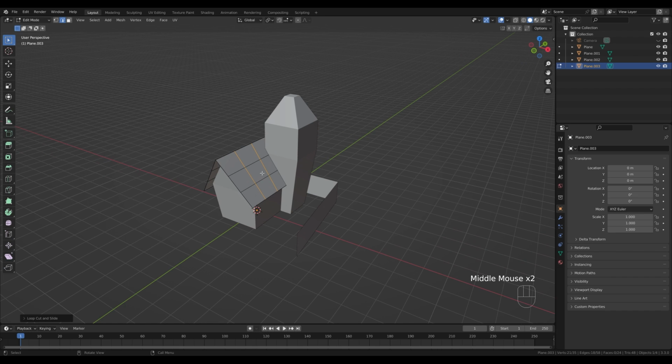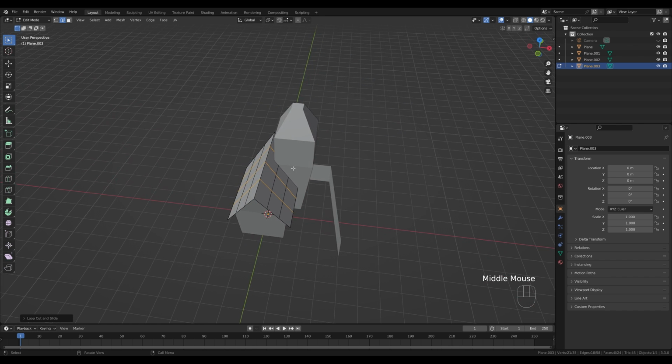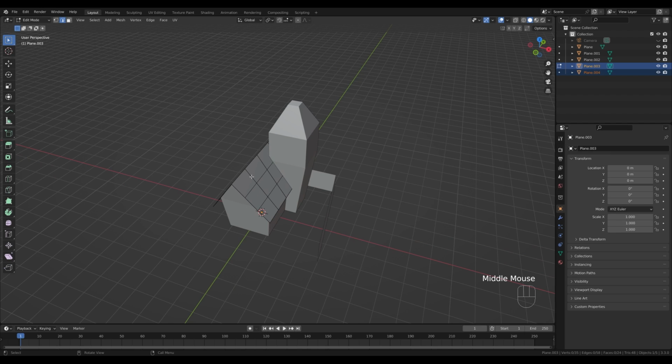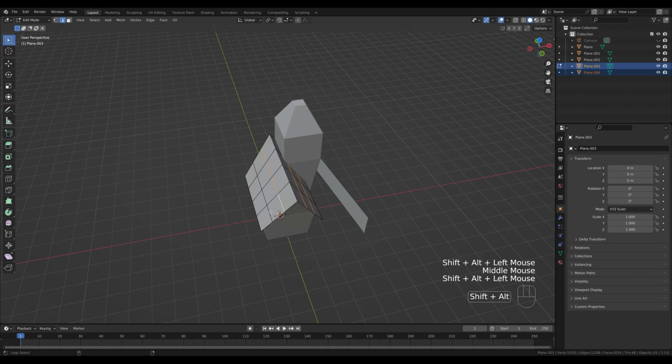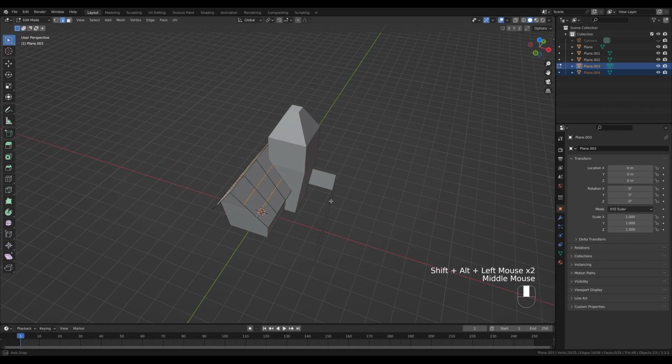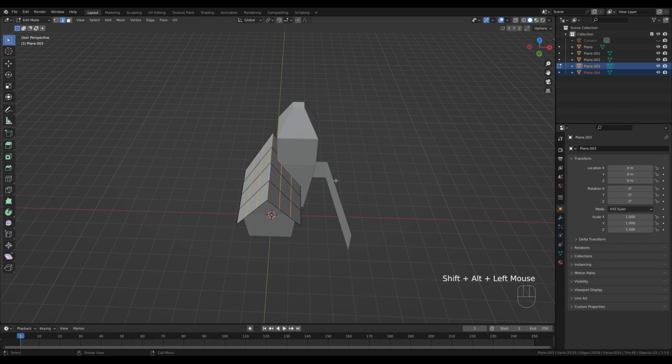And now to create the beams, I want to use the curves, but first I will need to separate them. So with these selected, I will just press P and Enter to separate the selection. And since these are edges and they're part of the underlying mesh, they are basically just copied into a new object. They stay here as well, and they're in the new object. So now I will Alt click this loop right here, and by holding Alt and Shift, I will add to the selection and separate these as well. Don't forget the top one. Let's press P and separate the selection.